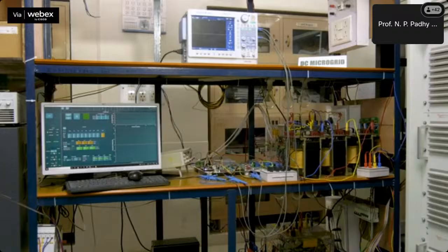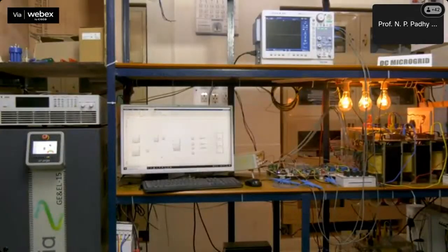At this MCB connection, bulb loads are connected in parallel paths and they act as a load to me. The other side of the MCB is connected to the output of the grid emulator, while the input side of the emulator is connected to the distribution system which is connected to our campus network. Also notice that after the inductors, the wires are passed through the LEM current sensor. For voltage measurement, sensing is done near the MCB input and the sensed signals are connected to the LEM voltage sensor board.